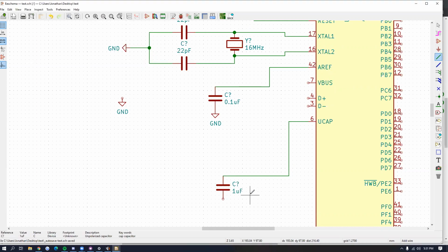How do you copy the capacitor? Basically, put your cursor on top of the symbol you want to copy, and then just press C. It's not letting me do that. I'm on the wire tool. It's kind of weird because sometimes you're on the wire tool and it lets you do stuff like that, but then sometimes you have to click on wire again, then press C. So wait, it's not consistent.